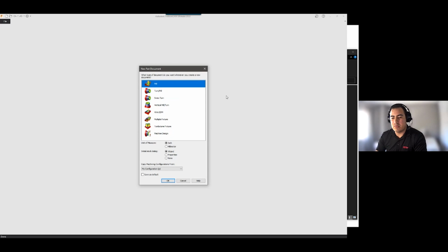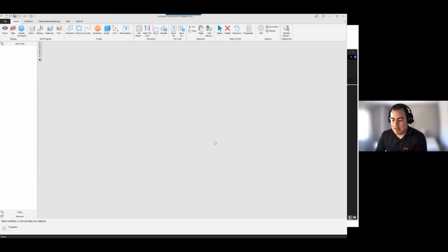You don't need to select any sort of feature in order to generate a toolpath for the CAM software. Another thing with FeatureCAM is that there's a lot of automation built into the software. For instance, if you look at what's taking place here in the first screen, it's bringing up a dialog box. You will see these throughout all of FeatureCAM. They're essentially what we call wizards inside of here.